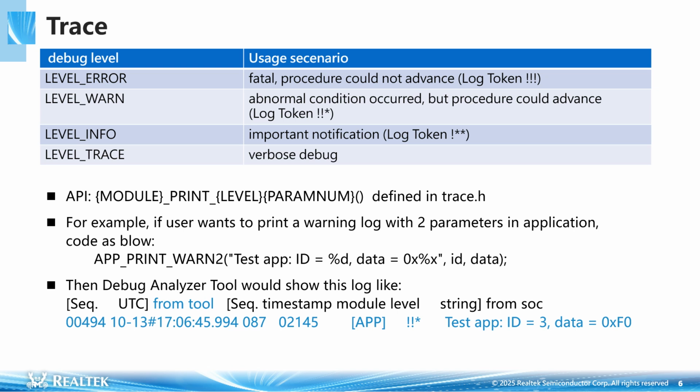The format for writing the print function is shown below, and the log tool will print richer string information correspondingly. It is important to note that the first 2 positions, namely the serial number and timestamp, are added by the log tool when it receives the log. Additional information, such as subsequent serial numbers and timestamps, is generated on the SoC side during the packet assembly. Because the package is placed into a log buffer and only printed when there is idle transmission space or enough logs have accumulated, if precise observation of the execution interval between logs is required, it is recommended to refer to the SoC timestamps. The precision is in milliseconds.